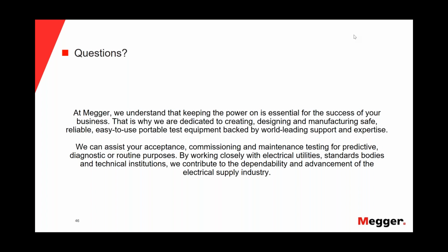But I will say that if you have a major issue, maybe if they mishandled the cable during the transport, if you do the PD test with the splices and the terminations, you will be able to detect that problem. So it's okay to do a PD test before putting the splices and the terminations, but I will say that it is not necessary. I don't know if Henning, maybe you have other considerations regarding this question.